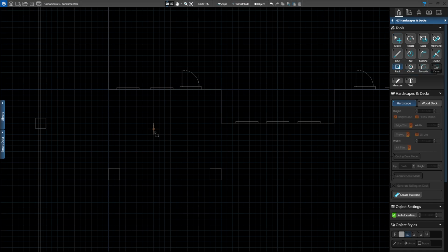We used this tool earlier to make our square columns, but we're going to make a rectangle. This rectangular patio is going to be 20 feet by 16 feet. So we'll left click and drag our rectangle tool to the desired dimensions and left click when you get those all laid out. So the way we do that is we go to our site reference, which is the bottom left-hand corner of the house.